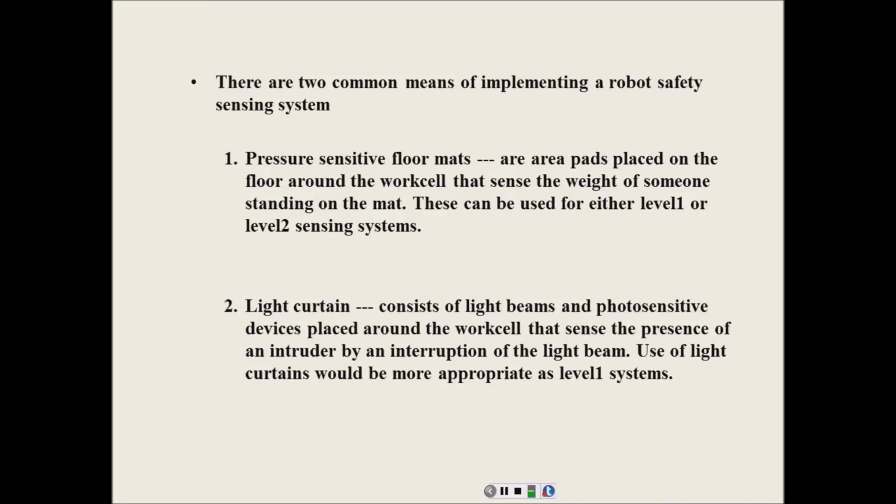These pressure sensitive mats are really neat. It allows you to open up the work cell, but the problem is they're pretty expensive, and they've got to be bigger than one stride. So that means you can't have one small enough for somebody to do what? Step over. But these are pretty neat in that what we can do now is open up the workspace, and if anybody steps on one of these mats, then it will stop.